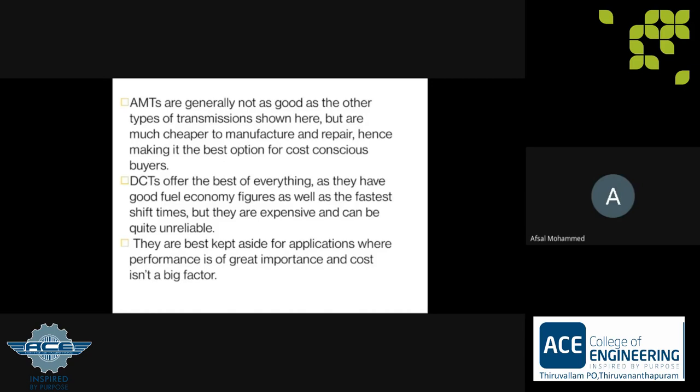Earlier, the Maruti Suzuki A-Star and others were offered as an automatic, but they used CVTs. And CVTs, even though they are easier to maintain, do cost more than an AMT. An AMT can bring the price down further, thus offering an automatic for people who are very price conscious, and people who are not focused on the driving experience. For example, people who use the AMT car as their secondary or tertiary car for small grocery runs only might not be as concerned with the shift quality, and they can easily go for an AMT and save a lot of cash.